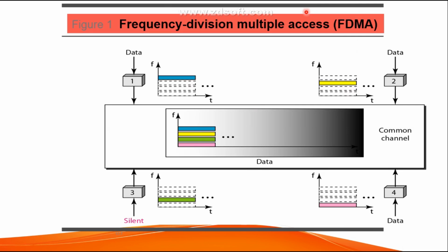Although you might think that FDMA and FDM conceptually seem similar, there are differences between them. You understood this diagram, it is very simple, but I want to emphasize the difference between FDM and FDMA. FDM is a physical layer technique. It combines the load from low bandwidth channels and transmits them using a high bandwidth channel. The channels being combined are low pass, and the multiplexer modulates the signals, combines them, and creates a band pass signal. The bandwidth of each channel is shifted by the multiplexer, as we already saw in our previous lectures.